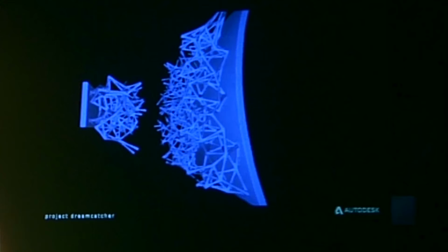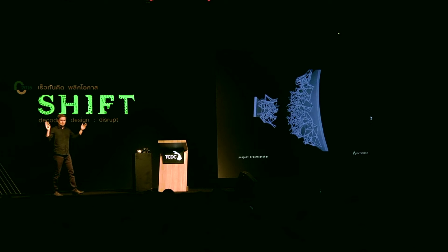So what you're seeing here is a very much slowed down video of a design that is being grown. And these two surfaces on either side are the constraints. So this is to grow a bracket, and we need to hold a certain amount of force at a certain distance, and we want to minimize how much this bracket weighs. Those are the objective criteria for this design. And so it grows a design, it evaluates its performance. Structurally, how does it perform? How much does it weigh? It ranks it, and it does it again. And the cool thing is, it does this about 3 times a second.